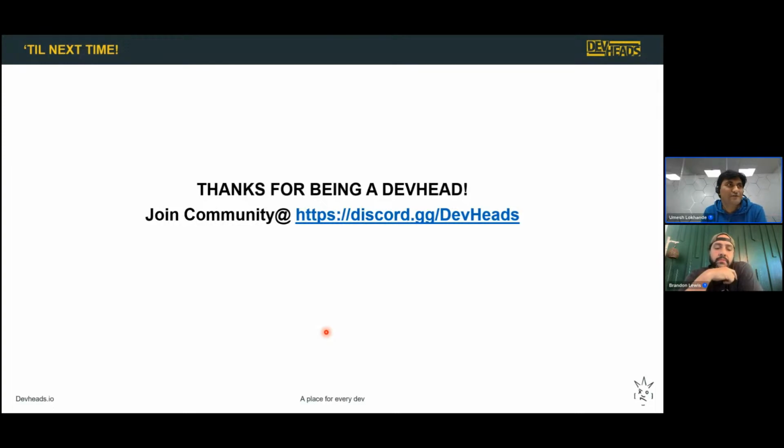You can also use DMA from the microcontroller to handle this very high throughput data. But if your requirement is as such, obviously you would just choose a microcontroller which has a built-in Ethernet controller. You can always have an option to interface external memory and offload your data if you want, right? That's why in microcontrollers these days we get a crazy number of interfaces like 4 SPI, 4 I2C buses, and a lot of other things.